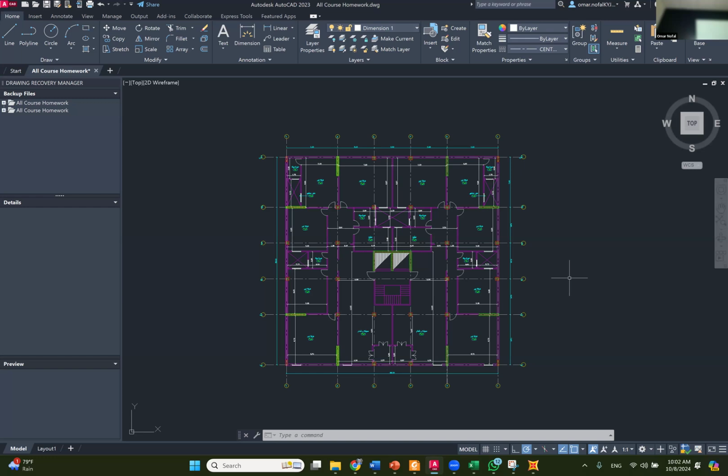This one. Why? Because this one is very stiff in this direction. This is my shear wall, this one. If the earthquake is coming this way, it's very stiff to bend that way, but this way it's very weak and can fall. Like when I put this book here, it's going to fall this way, not this way, right? Because this inertia is weak. Same thing, if the earthquake is hitting this way, all these shear walls, this one, this one, this one, are taking the earthquake in this way. That's why we put shear walls in both directions so that we can resist the earthquake.